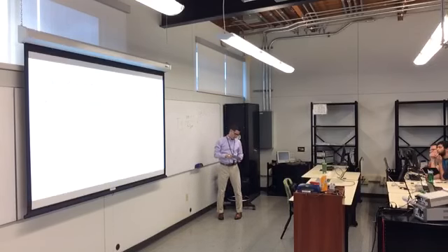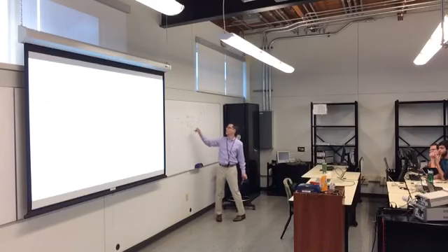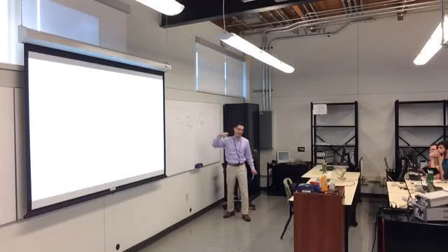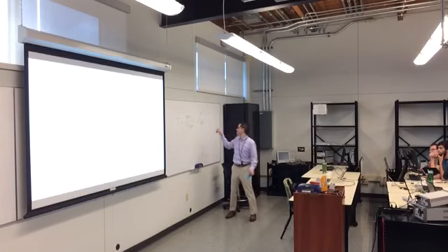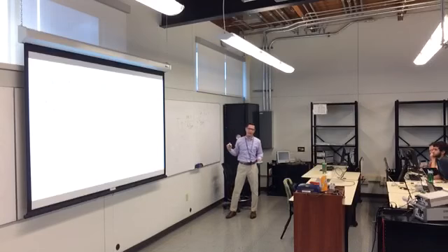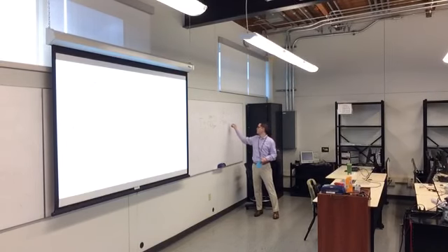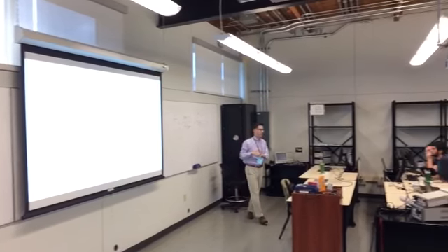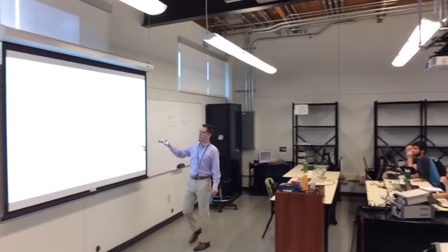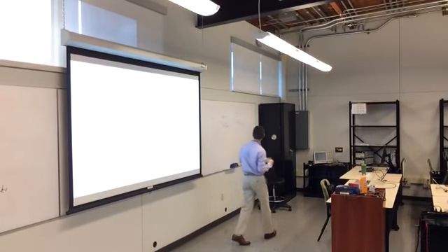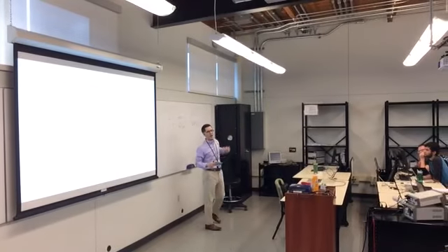Felix, what's the clock frequency I'm operating at here? All right, it's 25 megahertz. So 25 times 10 to the 6. Remember, mega is 6. And then Felix, how much am I scaling it by? So when I talk about a prescaler of 512, that means I'm going to take the clock and divide it by 512.